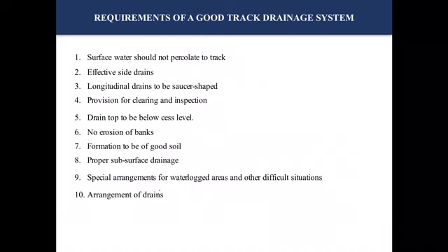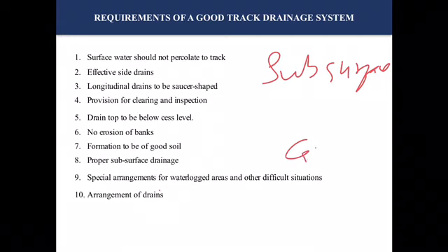And also the longitudinal drains should have proper, sufficient capacity, and the longitudinal slope has to be maintained properly so that it will effectively carry away all the possible surface water. And whenever it is required, we need to provide subsurface drainage. Subsurface drainage will usually be provided to divert the groundwater from entering into the formation. So we have various methods by which the groundwater can be prevented from entering into the formation level.